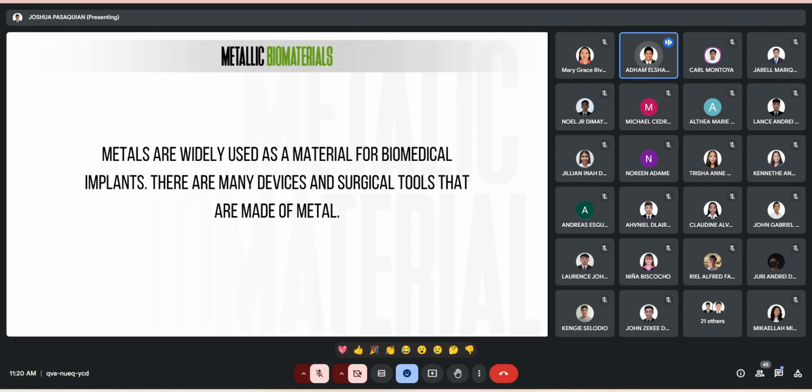Most of the metallic materials that are used as biomaterials have a stable surface oxide layer that improves their resistance to corrosion. The material should satisfy the needed mechanical properties for their application. For example, when a metal is utilized to augment a bone, the modulus of elasticity of the metal should preferably be equivalent to that of the bone. It can cause the loss of bone quality if the modulus of elasticity of the metal is greater than that of the bone. The bone will be remodeled to adjust to the lower load.